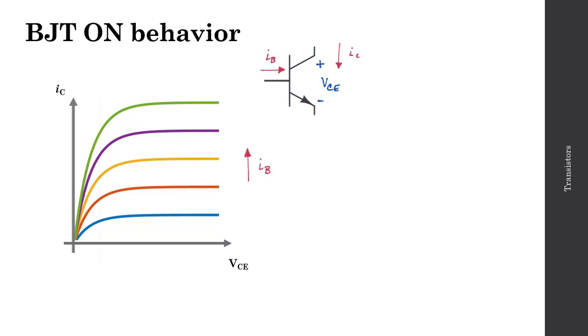Right off the bat, we see some interesting behaviors in terms of our plot. And to help illuminate some of these behaviors, let's draw a line of demarcation. So above this line here, I'm ending up with an amplification of my base current up to my collector current, and we'll refer to that again as beta. So this will be our current gain. If I'm in this region, we call this the linear region, I'm going to have a relatively uniform, relatively linear current gain.